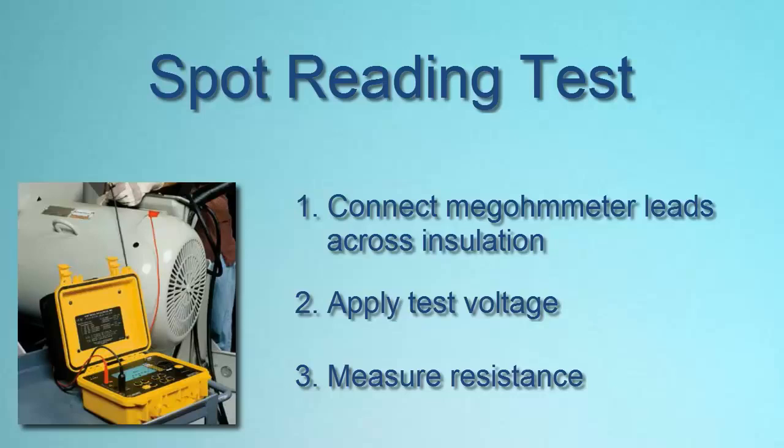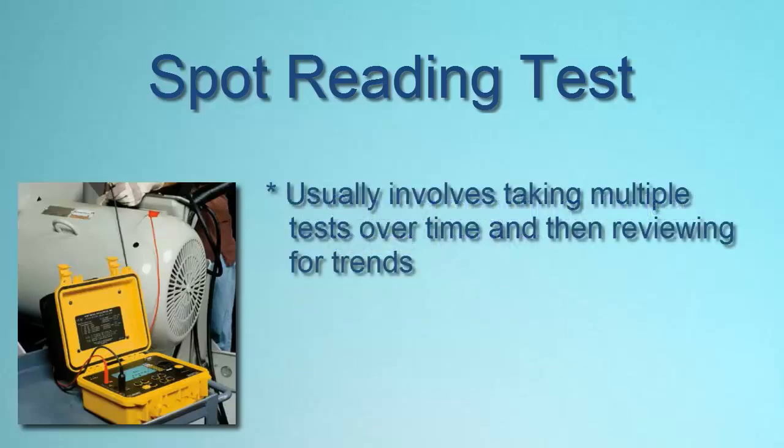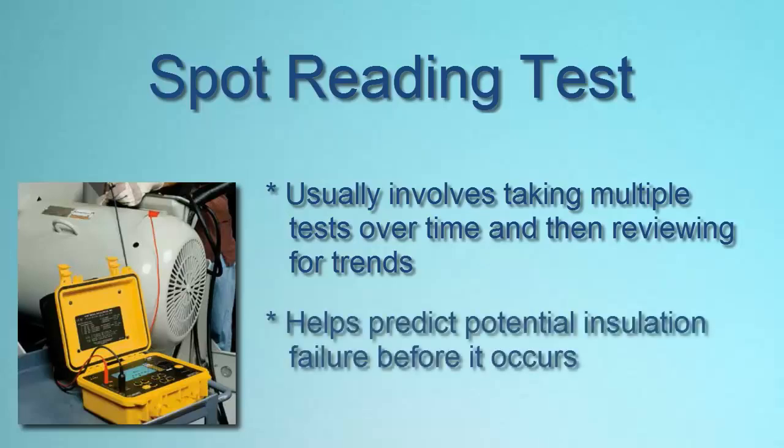A single spot reading test is of limited value, but the results become meaningful when a series of tests, all featuring the same voltage and duration, are performed over time and the results compared. This comparison can help predict a potential insulation failure in time to take corrective action.